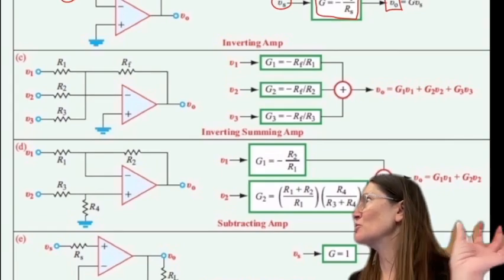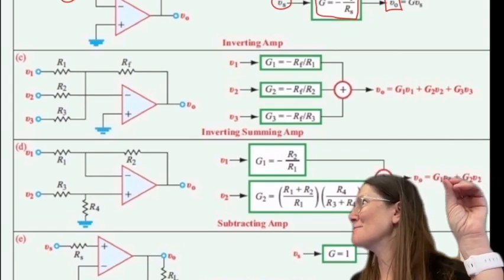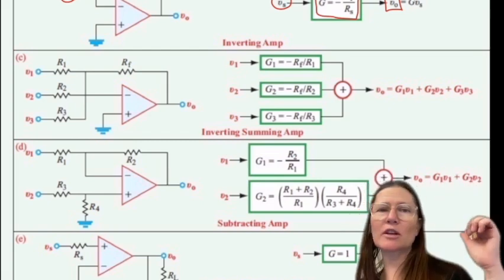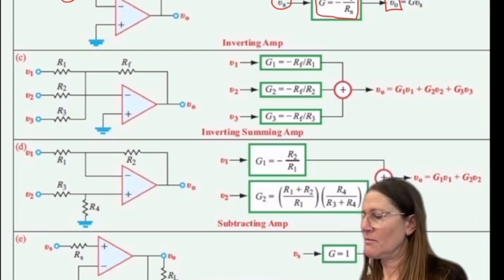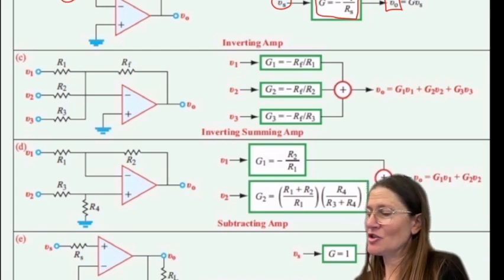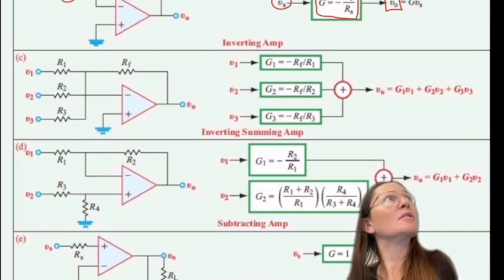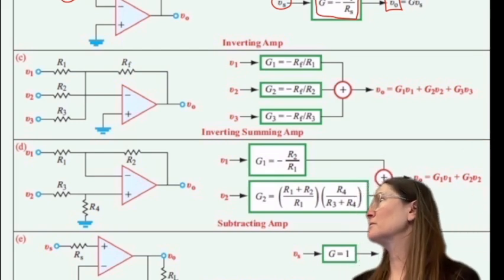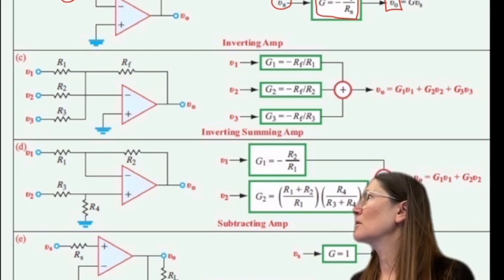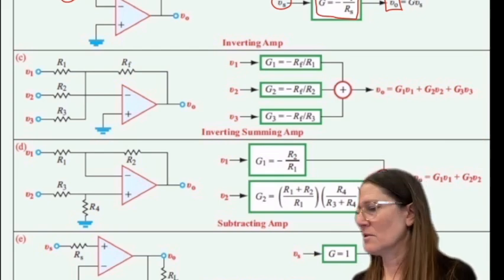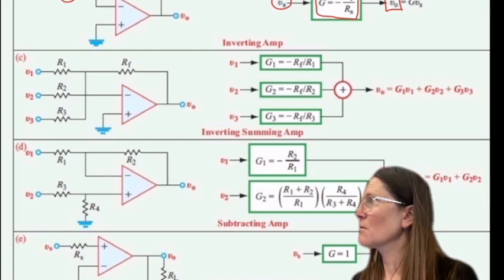So I was just showing re-deriving the equation again. But if you don't see that, you could do the same thing. With those zeros, then it's just going to be the RF over whatever resistor it is there. Yes. In that diagram, it doesn't have a voltage source going into the positive of the op amp, but in our example we do. How do we solve for that?